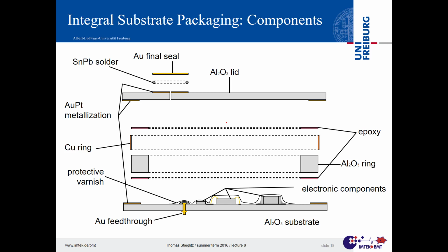Also, those pastes for screen printing had a lot of lead, and all the work was done by the Donaldsons to prove that this is stable. And we here redid it around 2000 to show that the lead-free pastes are also stable. So it's changing, but it was one of the last exemptions to use lead because of the reliability.